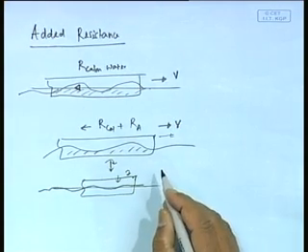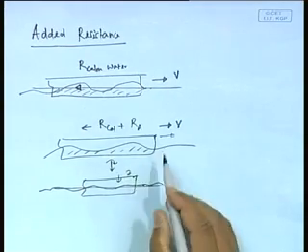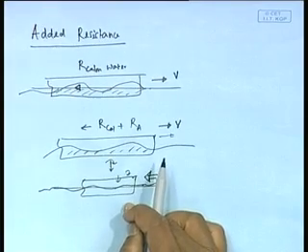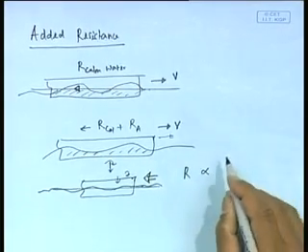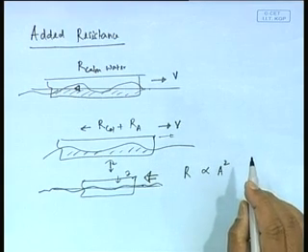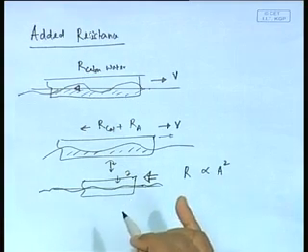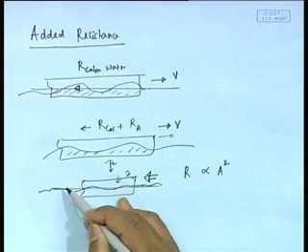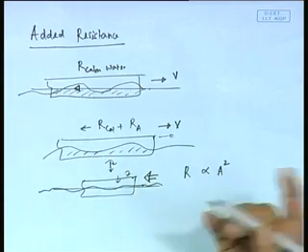this particular thing is normally going to be most significant in head waves, which I will come back to, but I can tell you one thing about resistance. Now, here there is the question: resistance is proportional to amplitude of wave squared. Here also the resistance that is caused is because of the waves it is creating. These waves it is creating would have a certain amplitude.